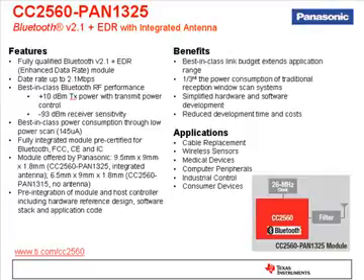is the RF performance, plus 10 dBm transmit power and minus 93 dBm receiver sensitivity. This is the best-in-class RF performance that you'll find. What does this mean for your end application? This means that you can have increased range, more than what you would have with a non-TI device. Also the quality, because the device can adjust based on range to make sure that you're getting the highest performance possible. Another thing to denote is the power.